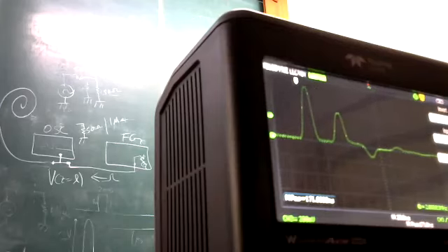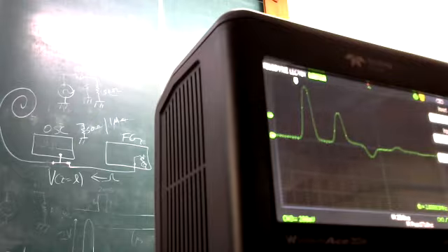Right. So the cable is open ended? The cable is open. The returning pulse is again seeing the effective resistance of 25 ohms. Then we have again a 1/3, if you look at 50 and 50, of the input impedance of the function generator. Then the junction, the boundary condition, is not matched, and then there's a reflection.